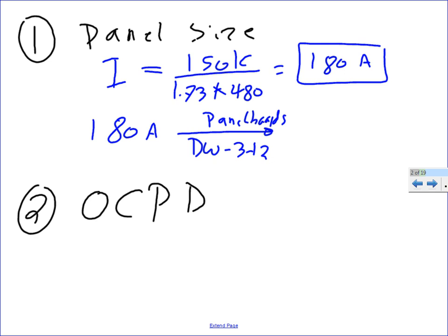Okay, can you guys see on the top of that page, it has the standard industry three-phase? So I have 180. What's my next standard from 180? Can you guys see that? My next standard is 200. Everybody can see that? So my next standard amp panel that I'm going to install in my building is 200. Any question about this? Everybody knows how to size the panel. Number one is the actual copper inside the panel. The copper inside the panel. Okay?